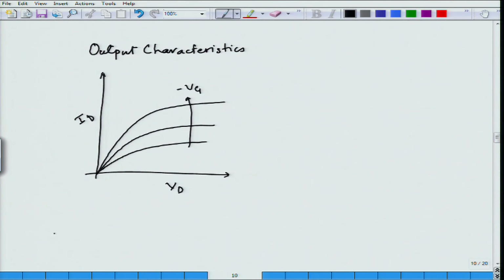And what is happening in the device here is that I have the gate and the dielectric, and then the drain and source and the semiconductor. So, when there is a Vg applied, initially there are no carriers. My V drain is 0 and Vg is 0, and the source is anyway grounded. At that point there are no carriers in the semiconductor and I have no current.